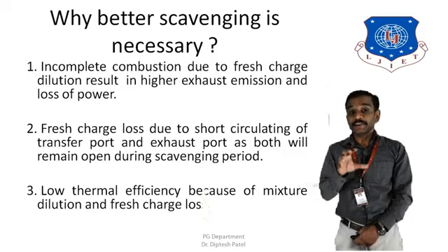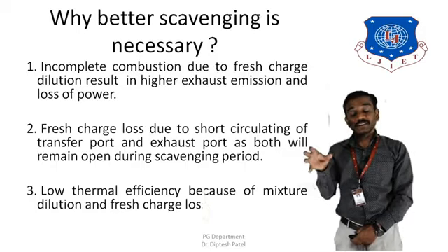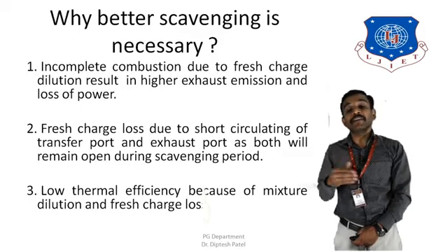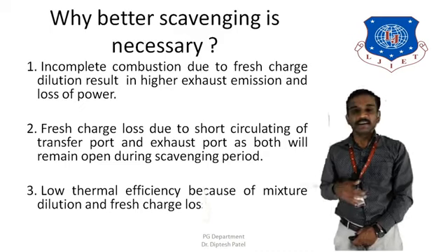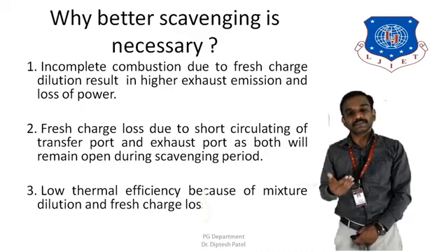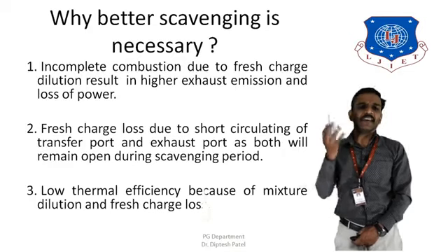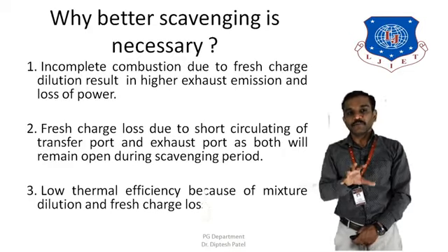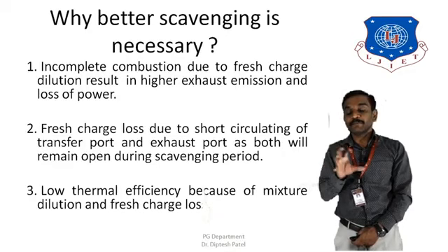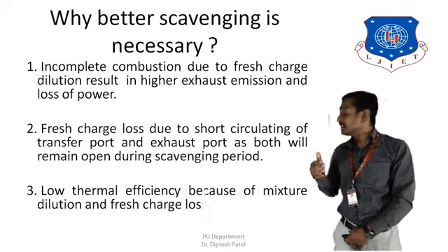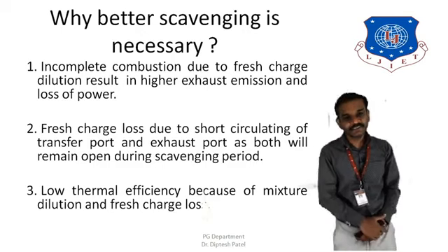If they dilute the fresh charge, the fresh air and fuel mixture, then the overall power would be reduced, and the emissions and pollution coming out from the engine cylinder would also increase. Therefore, these incomplete combustion gases need to get out of the cylinder.